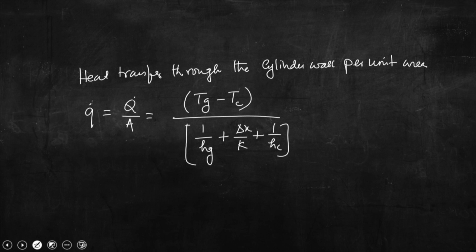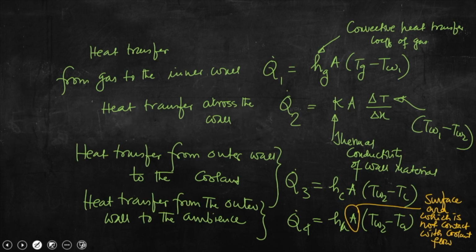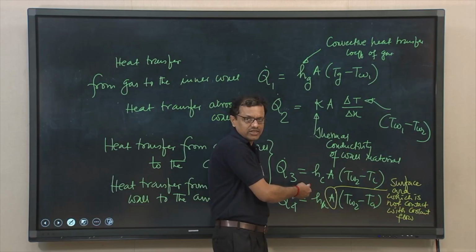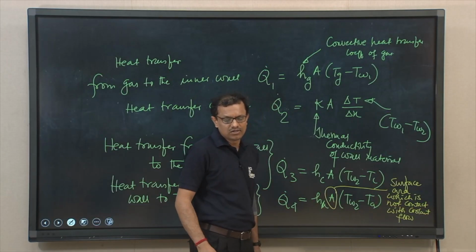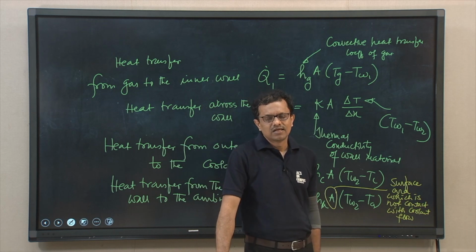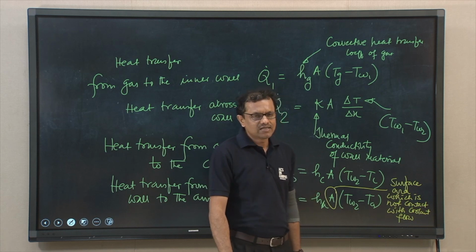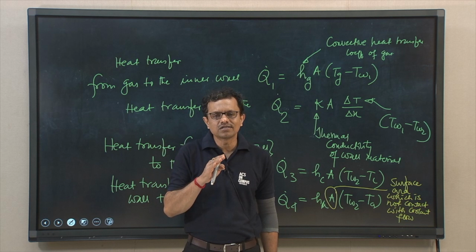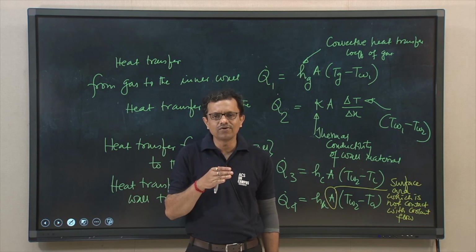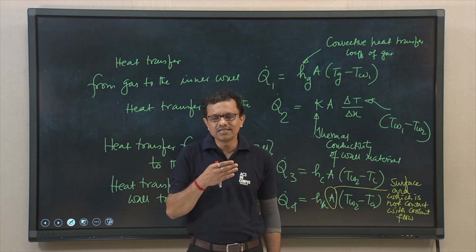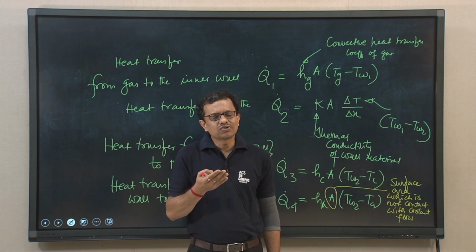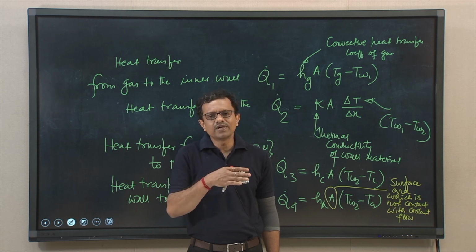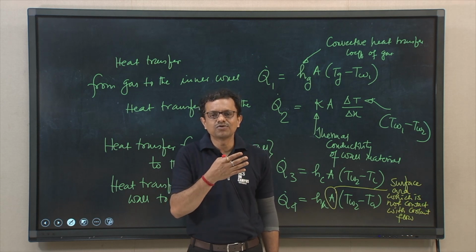So, try to understand, in this expression we did not consider this quantity. As I said, theoretically this quantity should also be taken into account when someone is designing the engine block or heat management in the engine. But as I said, from the schematic depiction it was clear that portions which are not in contact with the coolant flow are insignificant, and also convective transport of heat, because there is no air flow, is trivial as compared to the transport of heat by the coolant.